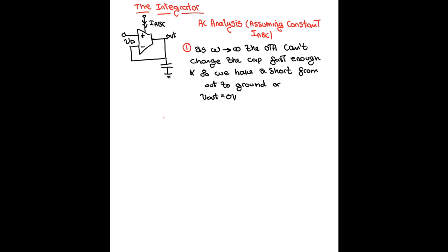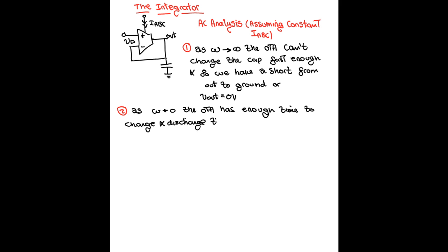Okay, so now the second case will be when the frequency goes down. So as omega goes to 0, the OTA now has enough time to charge and discharge the capacitor, and therefore, or thus, we have that the output is following the input.